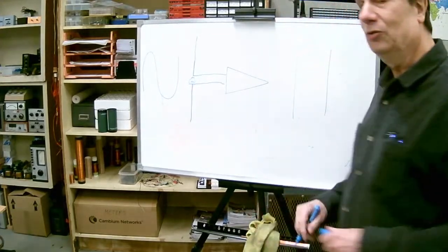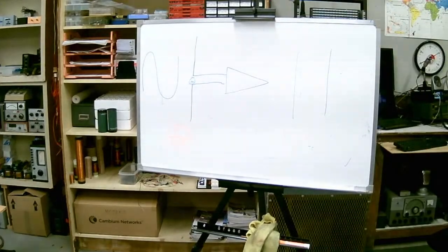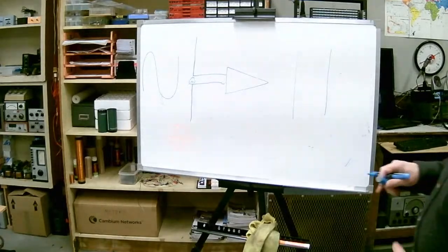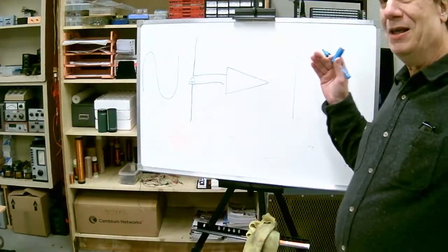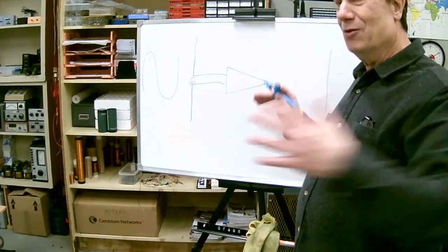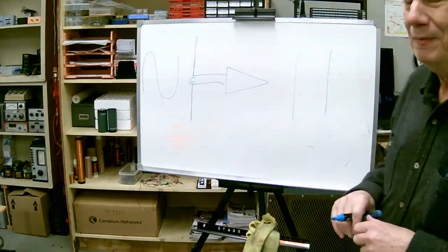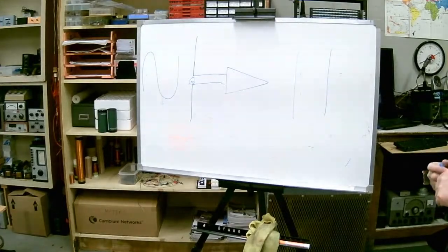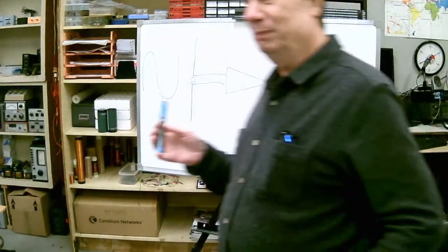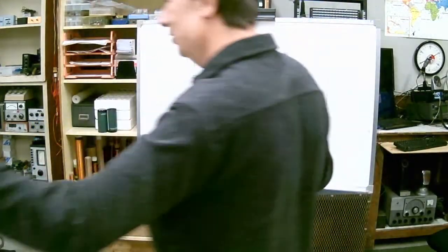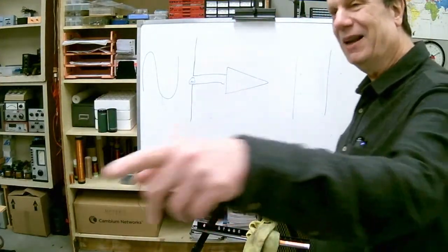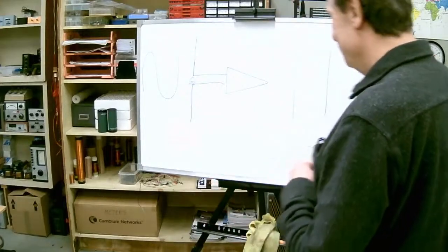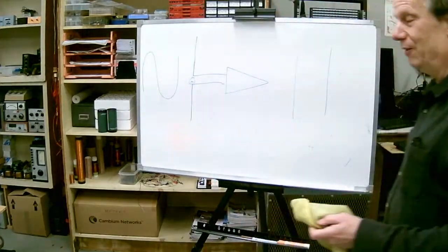Two antennas very close to each other can also have magnetic coupling, and we talk about high gain antennas to do that. But generally, when we talk about this reciprocity thing, we assume the antennas are far enough apart that they have no direct interaction with each other. That's what we call the far field behavior. As we start moving two conductors closer together, you start getting the magnetic coupling, just like you would with two coils. That's your near field behavior, which is a little bit different.